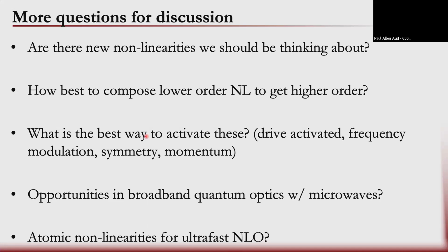The problem there is the instability is super handy because you get divergent amounts of gain at finite pump power. When you remove the instability, you get a linear gain, right? We saw 50 dB parametric gains, right? We do that because as you crowd in on the instability, you can get arbitrary gain. We can get 50, 60 dB too. When you remove it, 10 times more gain is 10 times more pump, which even for us is like fridge catch fire.